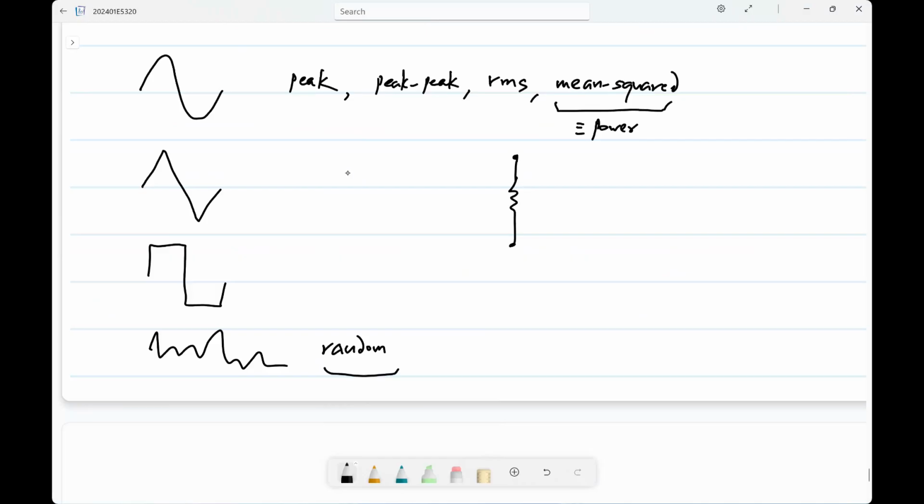Even when we do analysis with signals and block diagrams where there is no circuit and no power dissipation, we still refer to power of the signals. What is meant is the mean squared value. So that's what we'll try to calculate, the mean squared value of noise or something.